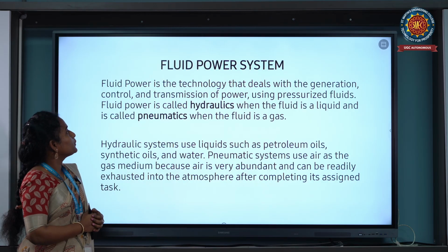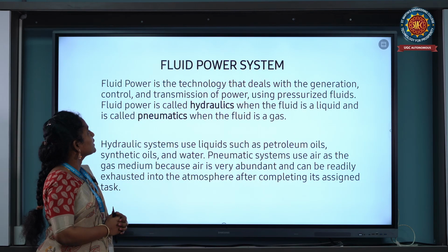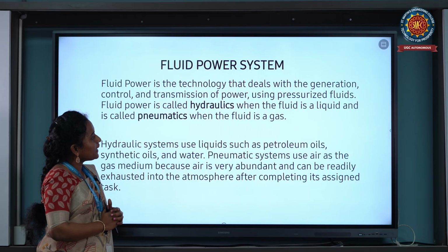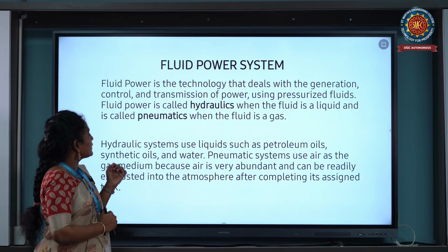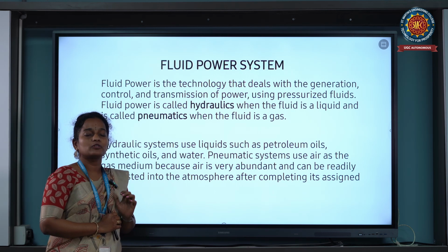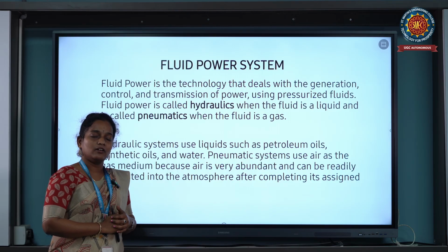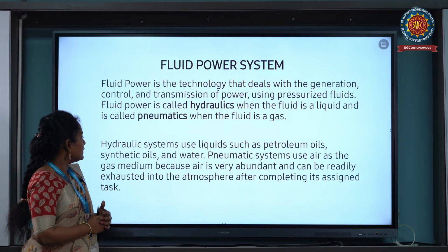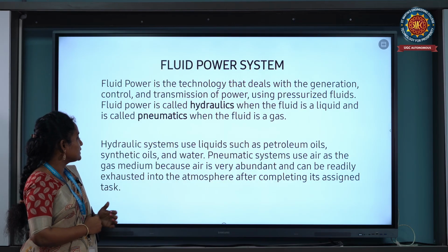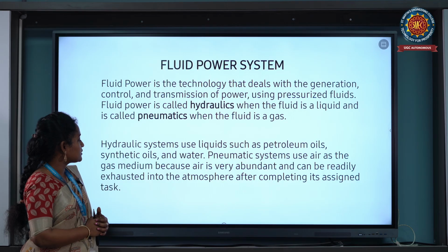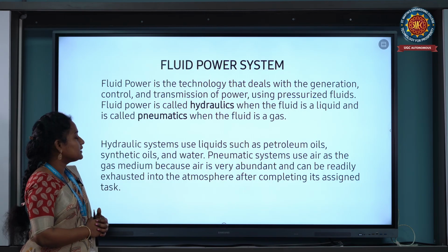Fluid power is the technology that deals with the generation, control, and transmission of power using pressurized fluids. Fluid power is called hydraulics when the fluid is a liquid, and pneumatics when the fluid is gas. Hydraulic systems use liquids such as petroleum oils, synthetic oils, and water, and pneumatic systems use air as the gas medium because air is abundant and can be readily exhausted into the atmosphere after completing its assigned task.